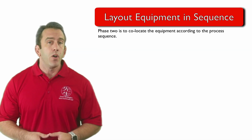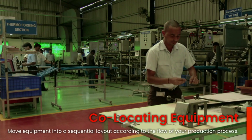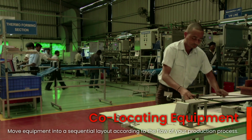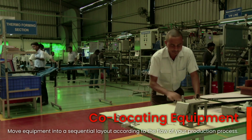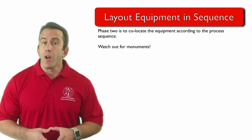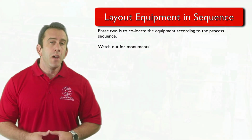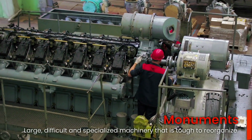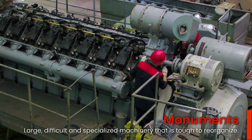In the pull it stages, step 3 is to co-locate the equipment according to the process sequence. This is where you move equipment into a sequential layout according to the flow of your production process. One challenge that you may run into is moving what are known as large monuments. Monuments are large, difficult, and specialized machinery that is tough to reorganize.